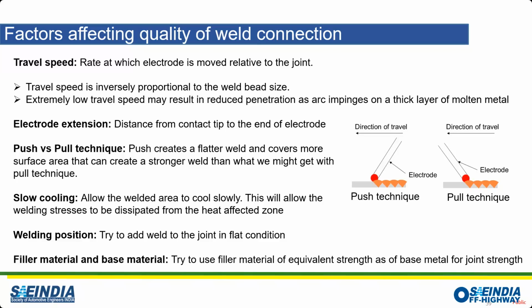Then be very thorough in choosing the filler metal. The strength of that filler metal needs to be very close to the strength of your base metal, so that will give you a good connection when you are doing the weld.